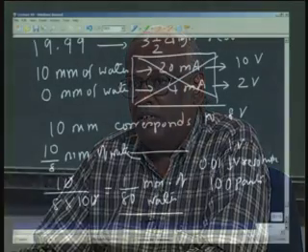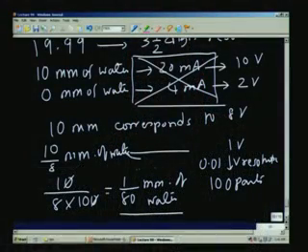Therefore, you see that in this particular case, by using a 4 to 20 milliampere current output and using 500 ohms as the load resistance, I can actually have a resolution of 1 over 80 millimeters of water column. That means that I can measure.